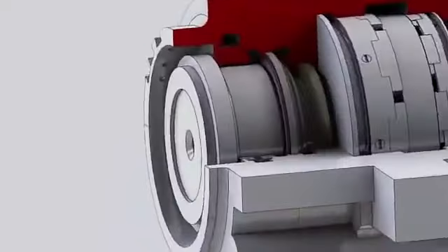Between the two rows of seal teeth, sealing air is admitted through multiple radial holes to stop oil from spreading along the shaft. Some of this air returns with the lube oil and is vented through the lube oil mist eliminator, and some escapes out of the housing.